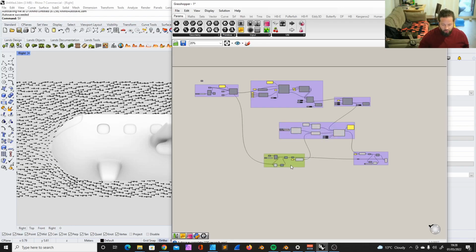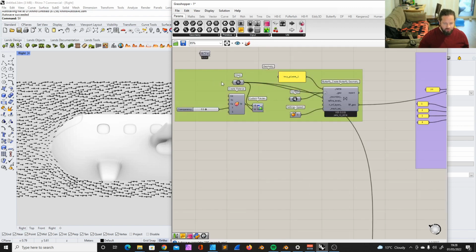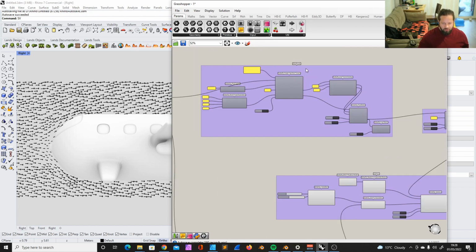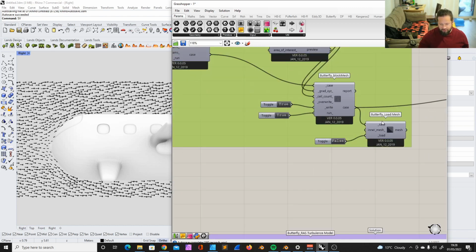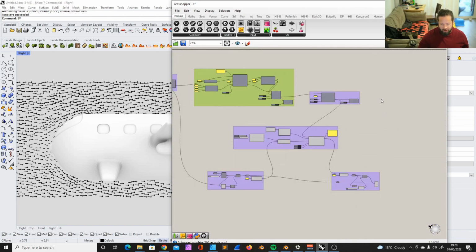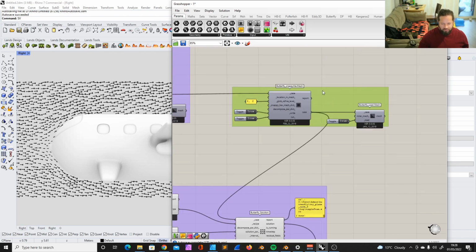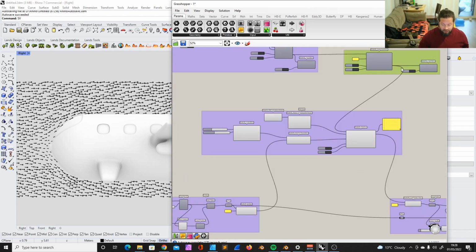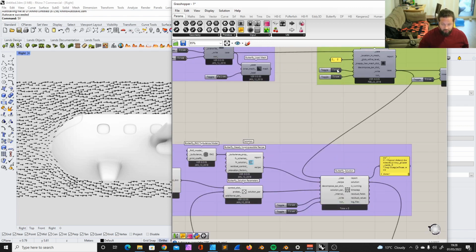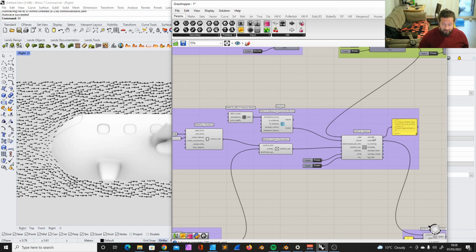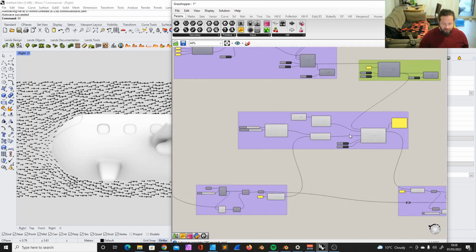Just for the people who already watched it, a very quick recap. We introduced the model, we created a butterfly model, then we introduced the wind tunnel and also the butterfly block mesh. And from there, we refined our model with the Snappy Hex Mesh tool, and we talked about refinement levels and so on. And then we created the butterfly solution, the actual core tool which does the calculation.